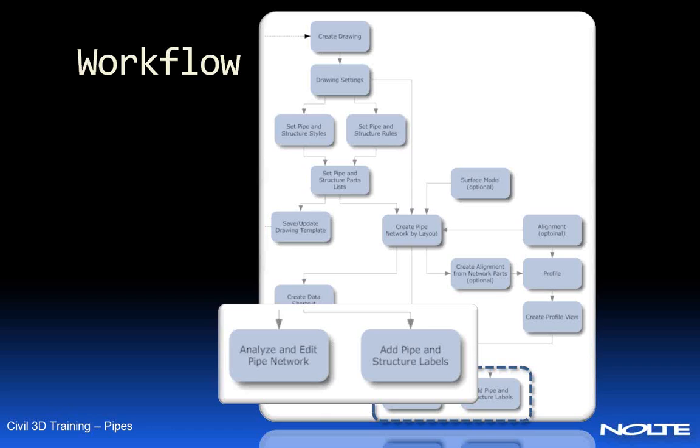If you want to use the Haestad applications or the MWH, we can export our pipe data to LandXML and then import it into whichever design application you want to use, and then we can turn around and import that back in. And I have a word of caution on that, is that LandXML is not perfect because each of the applications treat things like inlet structures a little bit differently, so I do have to edit and make some modifications every time I import and export. So it's not quite perfect, but they are getting there. All right, so that's the workflow I'm going to go through today.